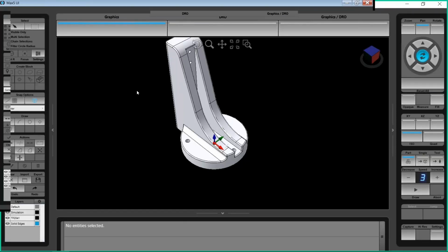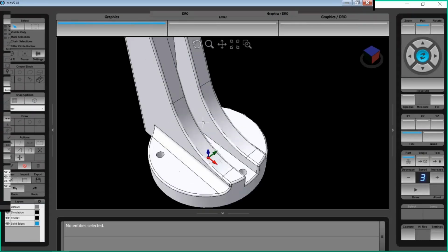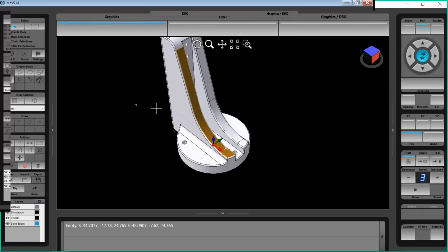So typically you would need to program a transform plane and then program a contour. But we do have a create block option called sidewall contour. So I'll turn my selection on and my snap functions off so that I can select a few surfaces here. I'll select one and press and hold control to select more than one at a time. So I've selected those surfaces. And now I'll go ahead and select sidewall contour.